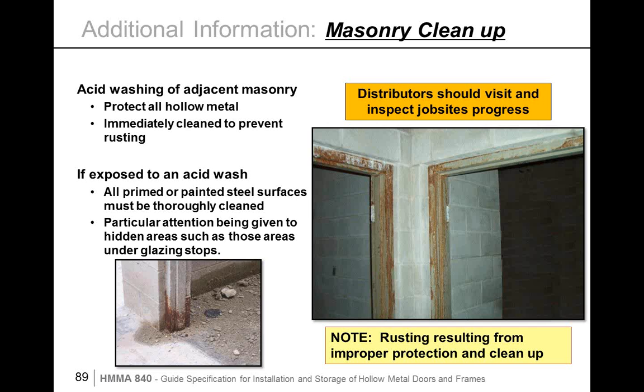In masonry construction, there's a lot going on. These frames are installed really early in the job, could be 6 months to a year before it is finished. So rust is critical. When they're installing the frames, it's critical that they remove any type of masonry residue.